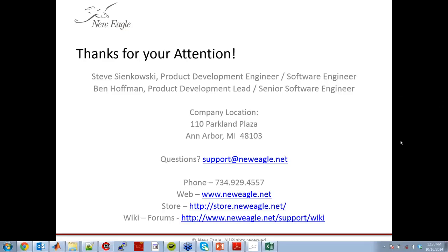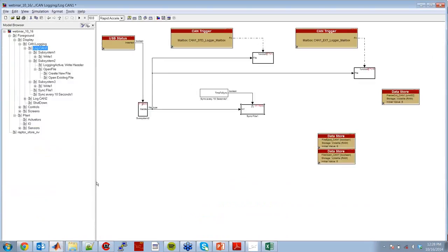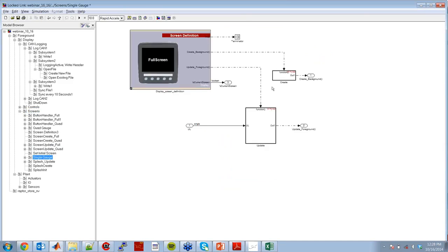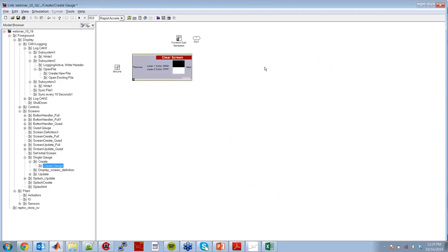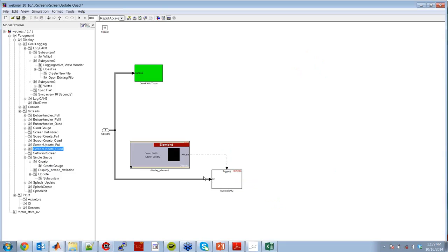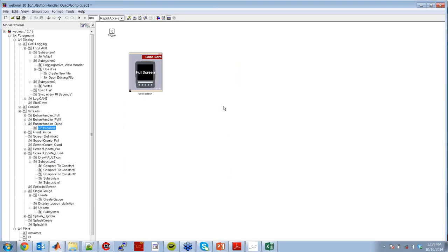There's some pre-built components that we include, like gauges, and in the standard way that a Simulink library block is composed, you can right-click and go under the library block and look at how the graphical elements are used to build something like a gauge. Obviously, with the gauge, you've got a lot of different elements, like the needle is rotating. You've got text that shows the current value. So you can go under and look at how that's done by breaking the link on the library block. And that can be a good example for how to build displays.